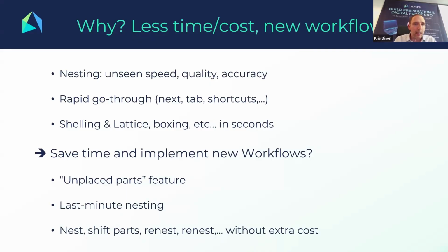Now, the workflows part, I will also demonstrate that in the demo, but you can very quickly move on with unplaced parts. You can do last-minute nesting by blocking previously nested parts. You can shift parts, re-nest, etc., without all that taking a lot of time.